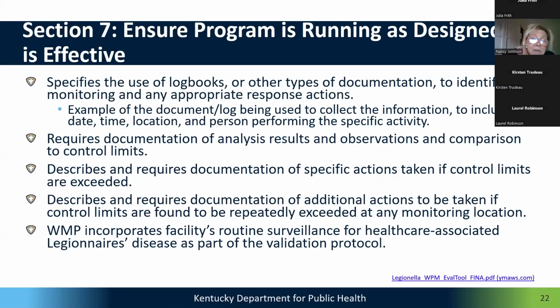You need to document your analysis results and observations and comparison to control limits. You need to describe and require documentation of specific actions that are taken, and additional actions if you still keep exceeding. And then you include your routine surveillance for Legionnaires' disease as part of the validation protocol.